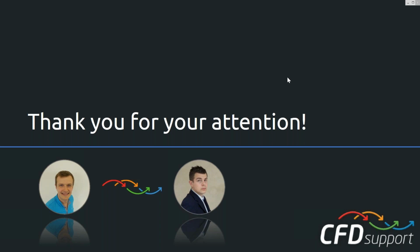Okay, and maybe the last question. Francesco has a question: how can you decide the level of gap refinement? What's the approach? Radek, do we know the exact number in advance, or do we just try it and take a look? Well, we can compute it. The clearance is the typical example, the gap between the blade and the shroud, and because you have the geometry, you know this clearance gap.